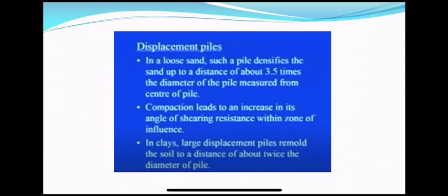When a pile is driven into the sand stratum, if the diameter of the pile is 1 meter, then around 3.5 meters distance around the pile, whatever sand is there in that area will get densified.